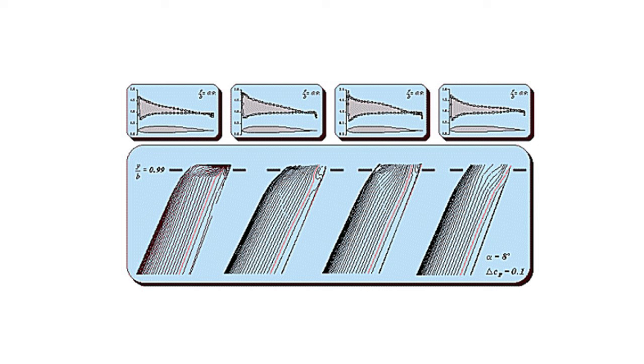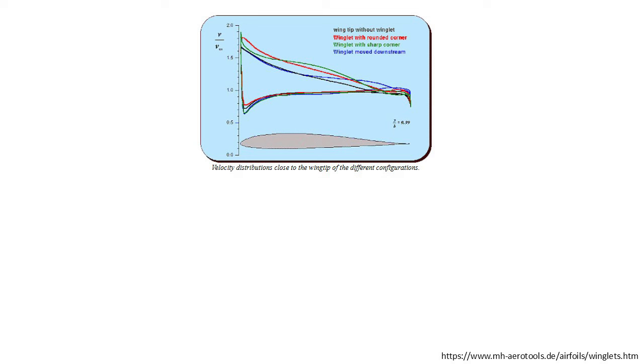We can also kind of decouple the pressurized regions of both airfoils here by simply shifting the winglet downstream. This just moves the wing's pressurized region closer to the winglet's pressure drop region towards the leading edge, and this partially cancels out the wing pressure rise, which leaves us with a slightly more favorable flow field in the wingtip region than if we had no winglet there in the first place. Moving the winglet downstream for low Reynolds number applications like UAVs or MAVs will just induce a larger region of laminar flow near the winglet.